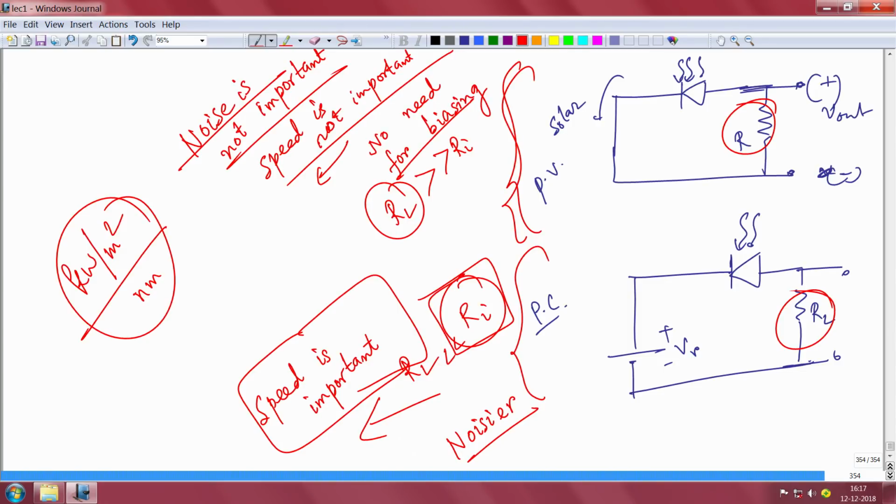The expression for the corresponding output voltage is like the open circuit voltage in a solar cell, except that here the wavelength is not that of sunlight but of the source, maybe IR, mid IR, maybe ultraviolet, whatever. Otherwise its expression is similar. It's just the junction photovoltage, 1 plus the photocurrent by the dark current. Nothing fancy. Photodetectors have very low dark current, very small load resistance and so on.